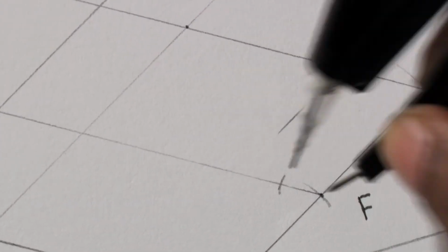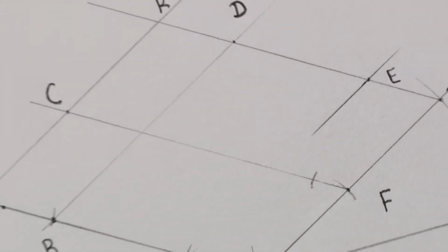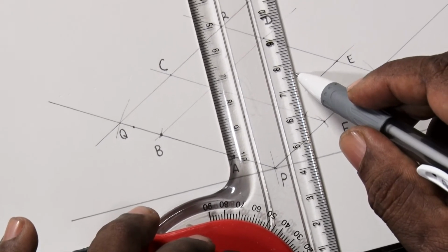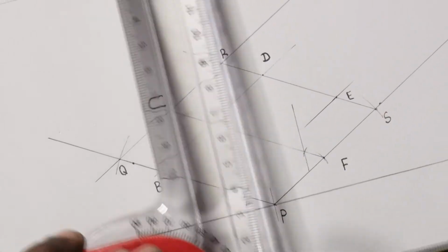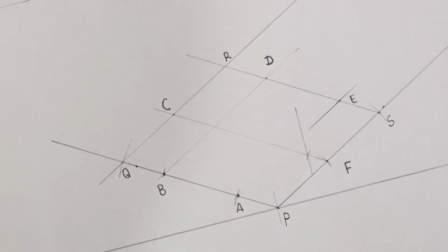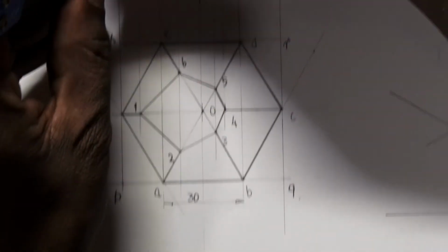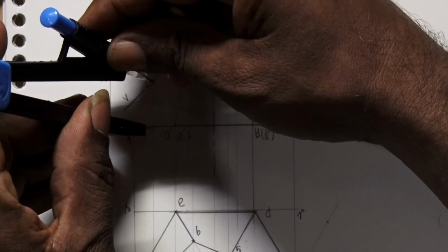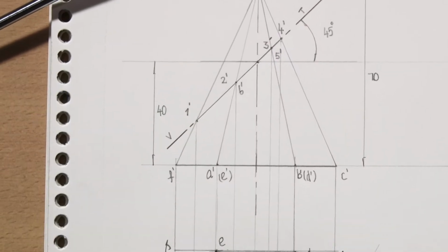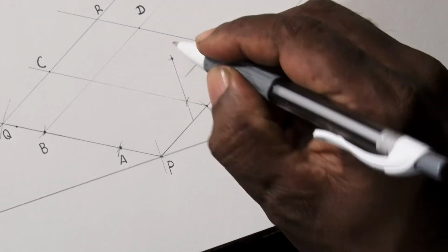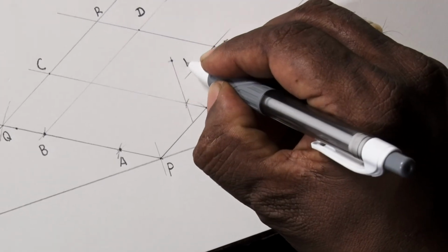This is the location, and we have to give the height. So we draw the height line through this, and we take the height line from the front view. So this is the height of 1. So we take this, and when we cut it here, we could get 1. So 1 is obtained.